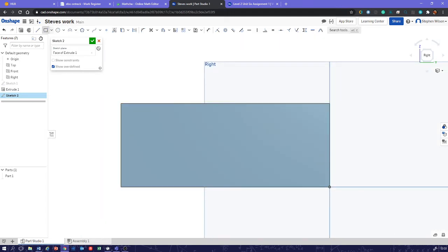Now you'll see that we've got that little T angle icon. There it's gone. It's back. That little icon that appears next to the cursor, and that's this here, is called coincident. And that means that we're locking the corner of our rectangle to the top line of our model. In this instance, coincident just means we're sticking two things together. Okay, right. So we've done that.